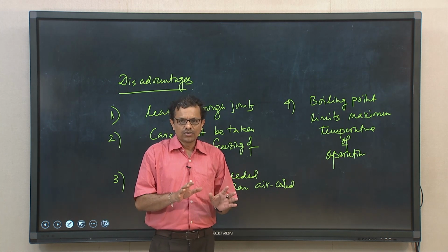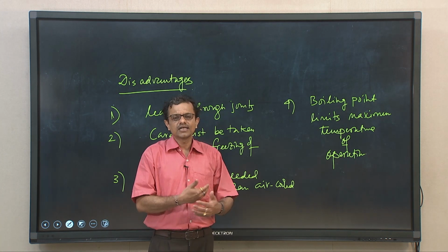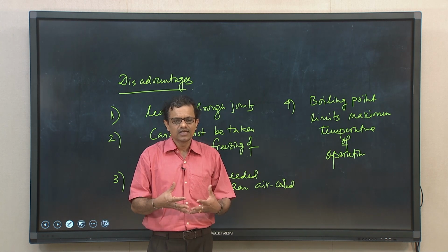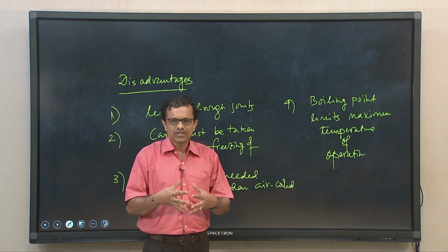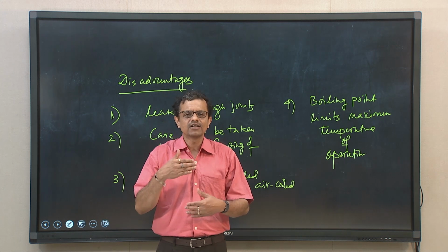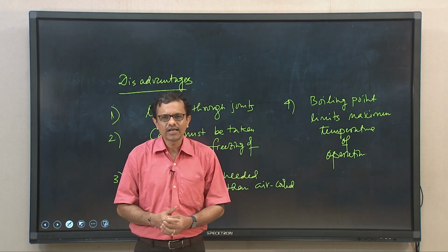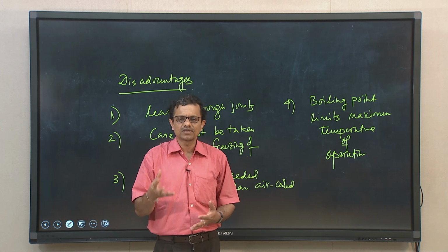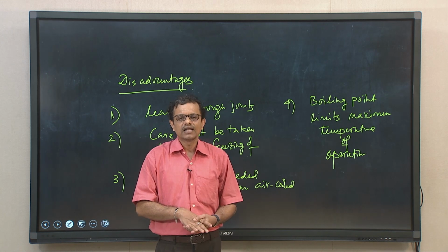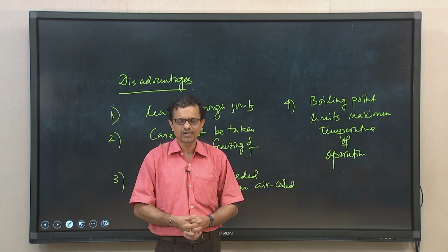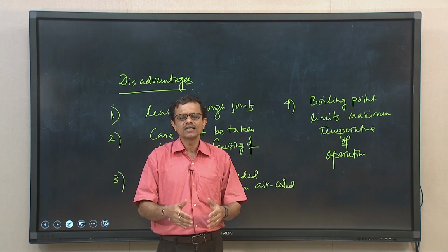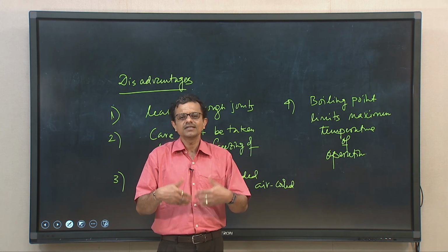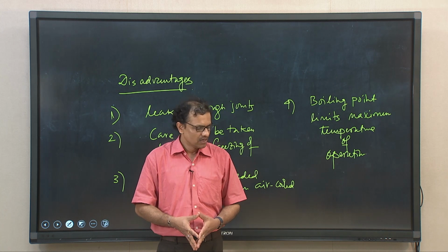So, knowing the advantages and disadvantages of the water cooled system, you can relate that thermosiphon cooling is a kind of extension of water cooling, wherein the need of an additional pump to supply water from the sump into the engine system will not be there, rather the system will rely on a natural circulation loop, and again if it is based on the natural circulation loop, some additional problems or issues will be there.